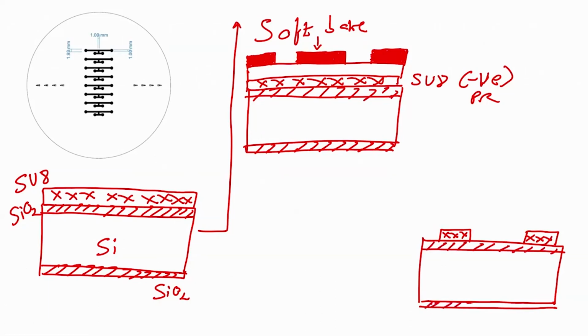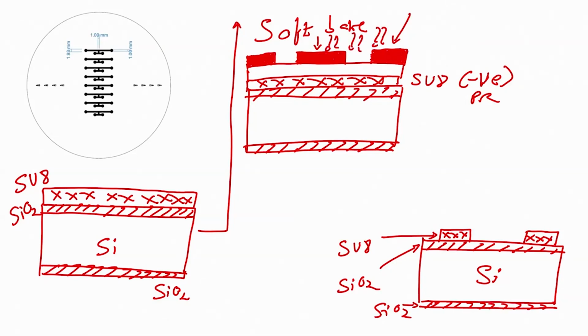Okay. And somewhere on the back side there is another pattern. So, this is a cross sectional view. So, you should understand this is SU8, SiO2, silicon, SiO2 here. So, to obtain this one we have to use the mask, which is shown here. After mask, what is the next step? Next step would be UV exposure.